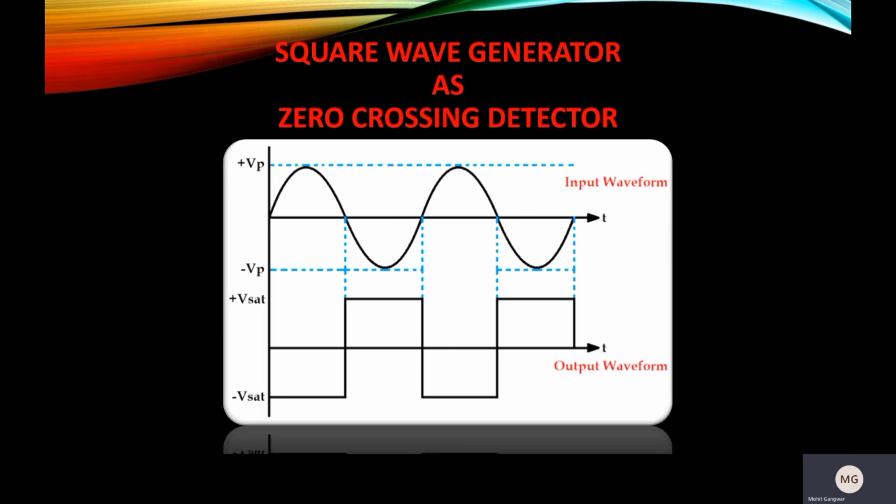of the op-amp changes either from negative to positive or positive to negative. It changes from negative to positive when the sine wave function changes from positive to negative and vice versa. In this way, the square wave generator can act as a zero crossing detector which detects the waveform crossing zero every time by changing its value. Zero crossing detector has many applications like time marker generator, phase meter, frequency counter, etc.